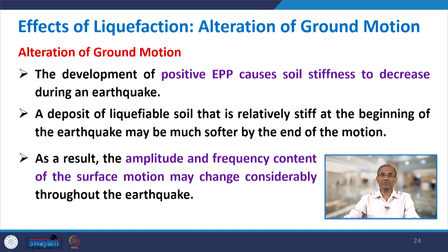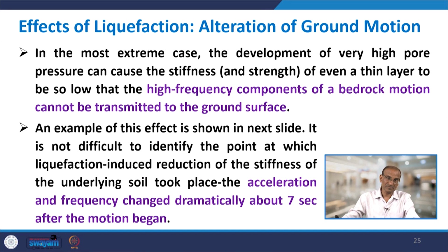As a result, the amplitude and frequency content of the surface motion may change considerably throughout the earthquake. You know that the natural frequency of a system depends on its stiffness. Due to liquefaction, the soil gets softened and loses its stiffness, and once its stiffness decreases, the natural frequency of the system will decrease, and the amplitude and frequency content you obtain will be different from earlier. When liquefaction starts, the behavior changes, and it will keep changing as the level of liquefaction increases.